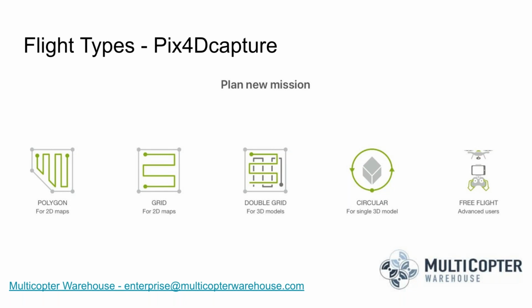That provides you a lot of flexibility, because you as the user can dictate how much spacing there is between front and side movements, or horizontal and lateral movements, so the drone will capture an image at every X units of measure. That really allows you to do what we'll call a vertical grid if you're trying to inspect the face of a dam, or maybe get a good ortho plane, an ortho facade, of the front of a building for architectural purposes.